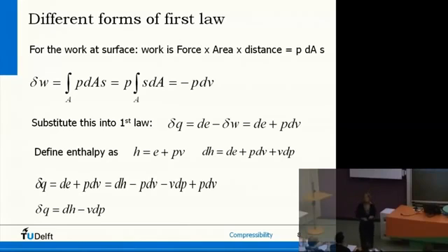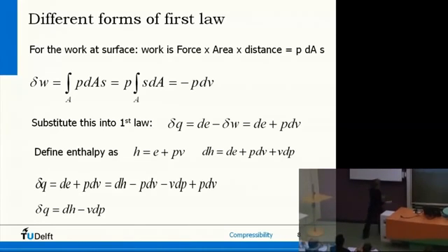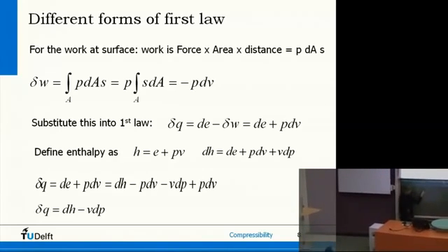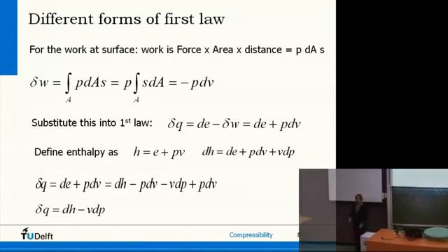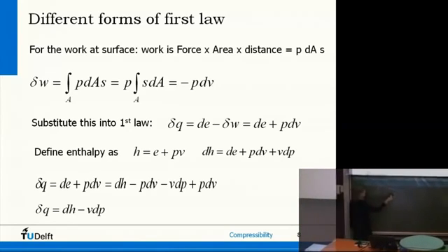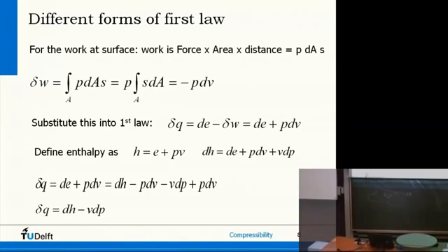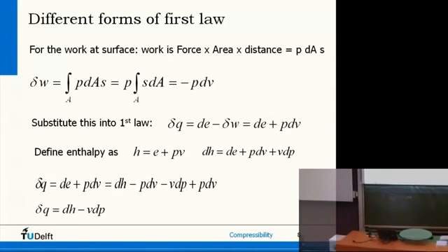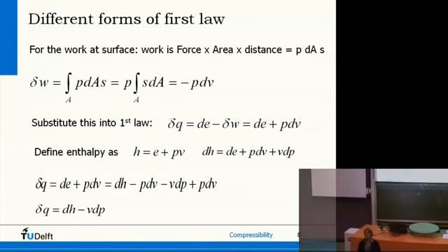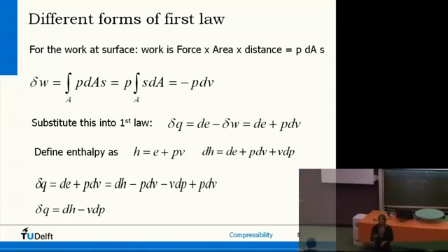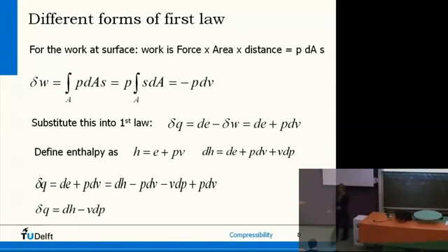Now, let's first think about the work done on this surface per unit area. So for this work done, we assume a small area dA, a boundary element of this unit mass. Now, what is it actually that might be pushing it in from scalar flow quantities? It's a force, right? What force do we have in our flow? Pressure. Pressure is a force per unit area. So we have a pressure around this, surrounding it. So in normal direction, we have a P on this small blob.